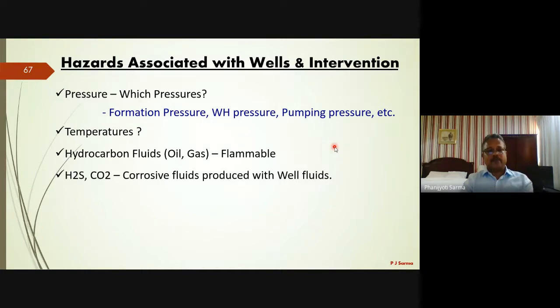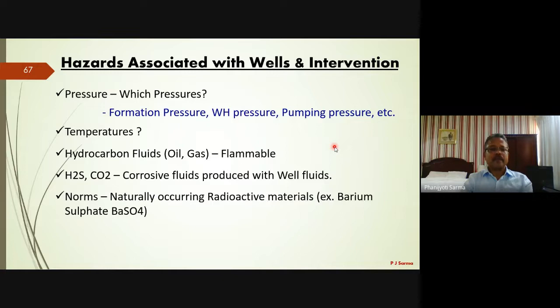Hydrocarbon formations also produce H2S, carbon dioxide, and even NORM, naturally occurring radioactive materials. It all depends on the formation characteristics. NORM is, for example, barium sulfate, which occurs naturally in the formation. So these are the hazards associated with wells.